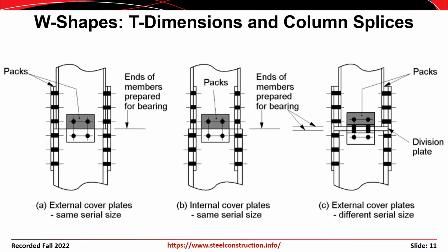This is another image, 3 images actually, that come off of steelconstruction.info. This is a European website. I think it's from the United Kingdom. And instead of calling them fill plates over there, they call them pack plates or packs. But similar idea, you're just using extra steel that's really not there for a structural purpose. It's basically there just to take up space so that when you bolt it together, you don't end up with bending and warping of the plates.